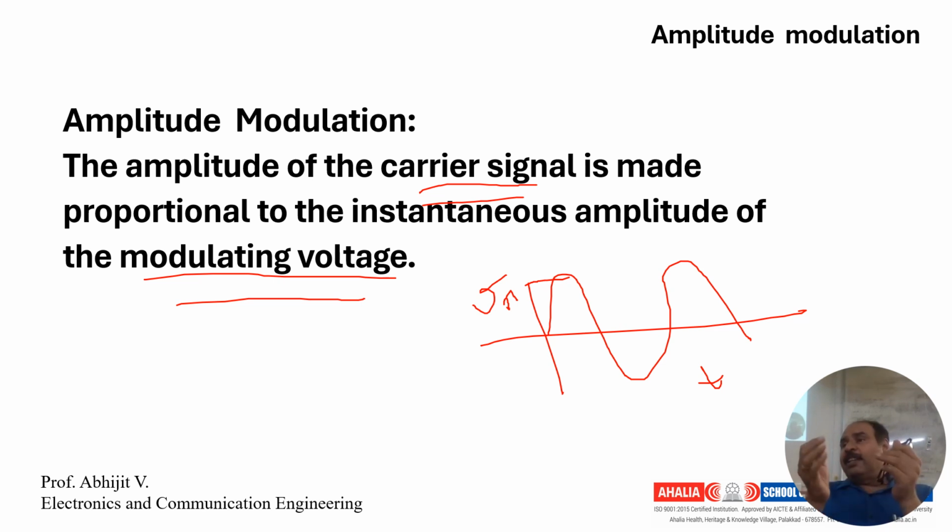Okay. So the carrier signal looks like the cover in a postal communication, and the message signal is what is put inside. So here you are putting this message signal inside the carrier signal so that the message is being carried by the carrier signal. So how do you define amplitude modulation? Amplitude modulation is a type of modulation where there is a carrier signal and this carrier signal's amplitude is varied with respect to the message signal. Understood all of you?